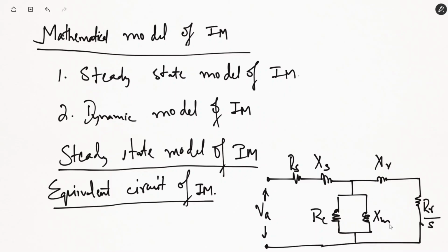As far as the equivalent circuit of induction motor goes, this will give you the steady state components of the induction motor. That is, it will help us calculate IAS, that's the current in phase A of the stator. Accordingly, you can calculate the current IR. You can calculate the rotor copper losses I square R. You can calculate the stator copper losses I square S RS.